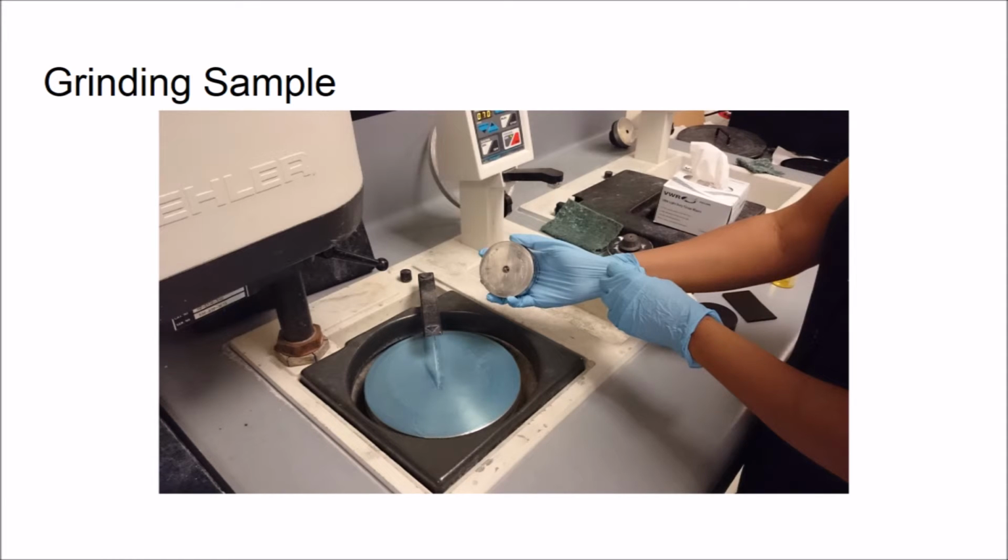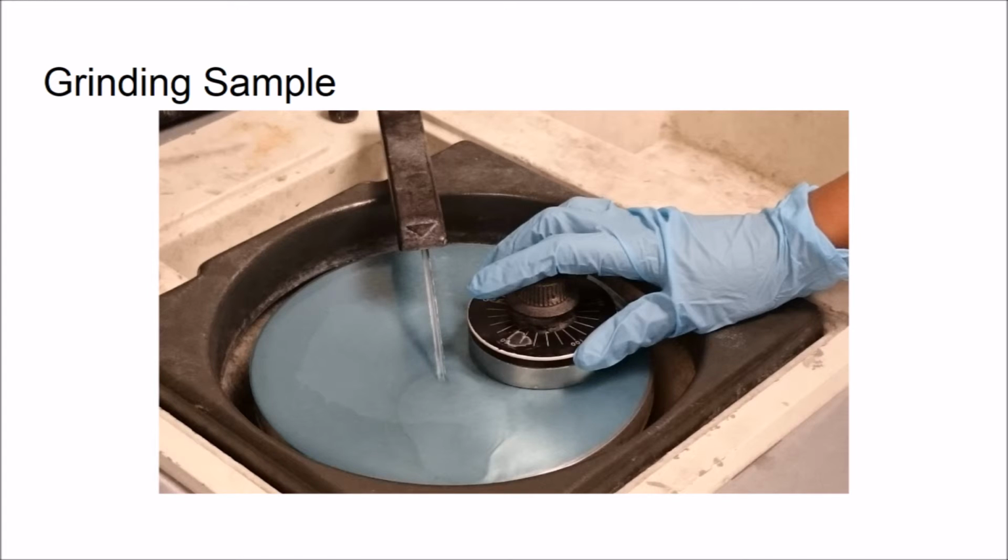Next, the sample will be ground down to make it thinner. The wax cylinder with the sample attached to it will be placed into a holding device, which will ensure that the sample remains level while it is ground down. Next, the sample will be placed onto the polisher, where it will be ground down by either a very fine sandpaper or a polishing cloth in a very fine abrasive solution. After this step, the sample should be less than 1/10 of a millimeter, or 100 micrometers.